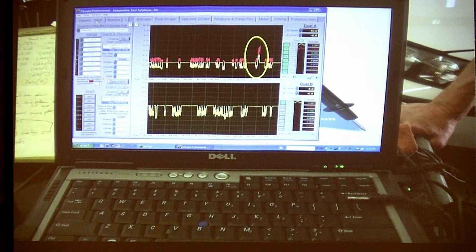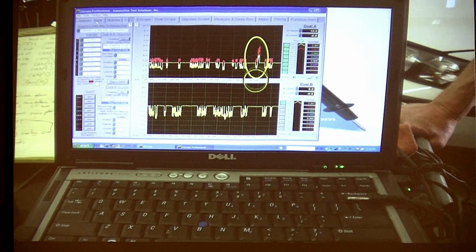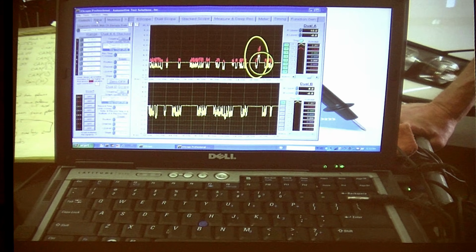If I stream it, I'm just watching the stream, and I'm watching for something to jump up, something to go low or high. Most of these that I see go either up like this or down, but the transceiver pulls both lines in one direction. That is a module failing. And when you do your scope stuff, don't have it on triggers for this. You'll miss it. Have it streaming. Just have a bunch of data coming across where you can watch what's happening in live time. Then we're going to try to figure out what module this is. That's a zoom in on it.